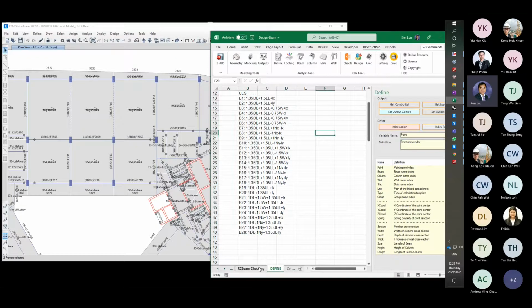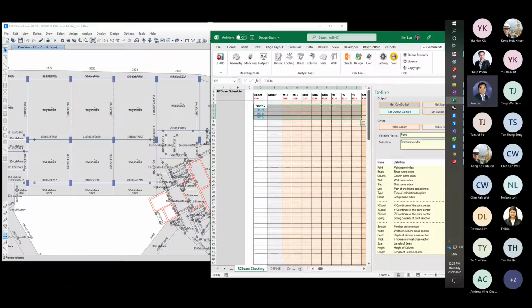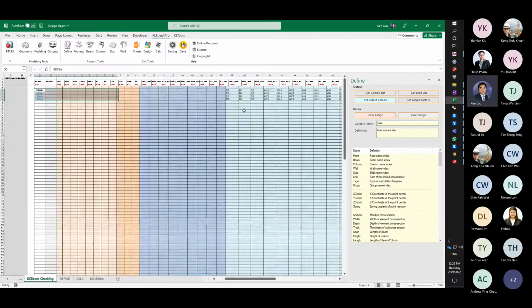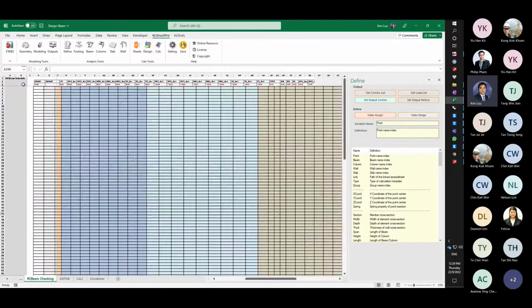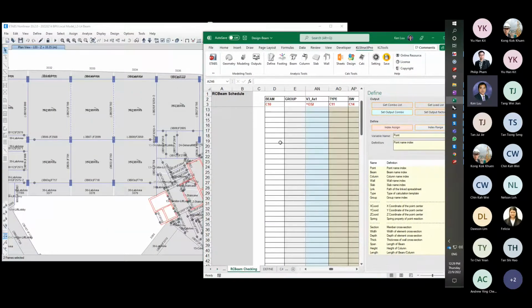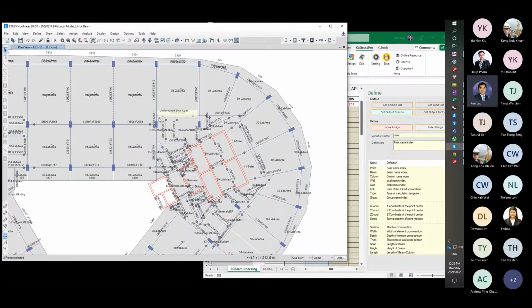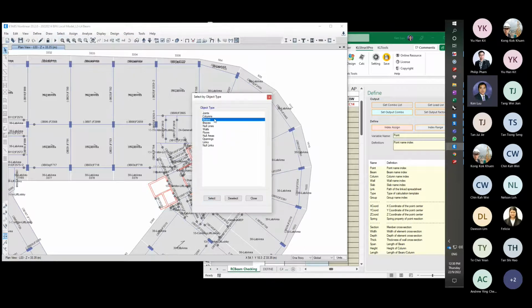So once I do this and I have the beam group already, this one I will delete everything. Delete every information here first. So I will go straight to show you the design step. Once you have defined a load combination, and now you want to design this beam. Actually, you can design all the beams. If you name them already, you can design all the beams at the same time. Let's say SS T. I will select all the beams now.